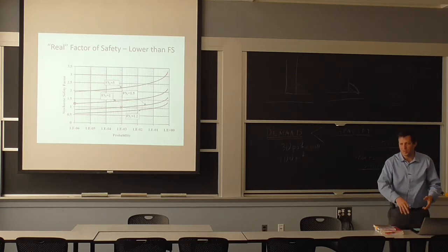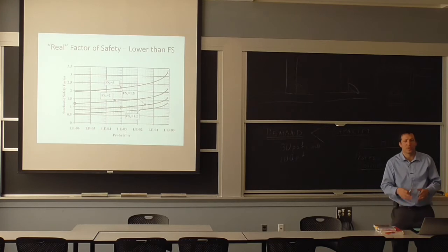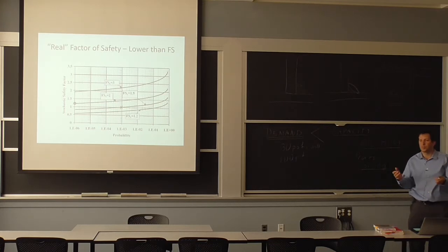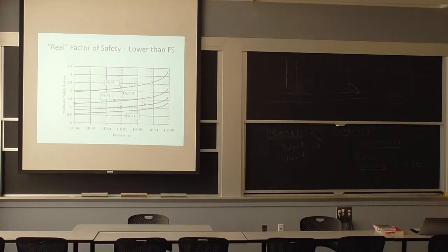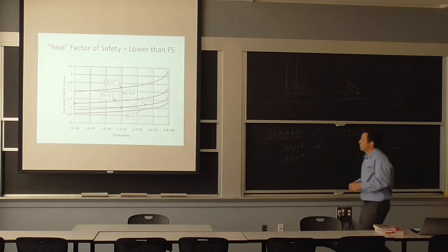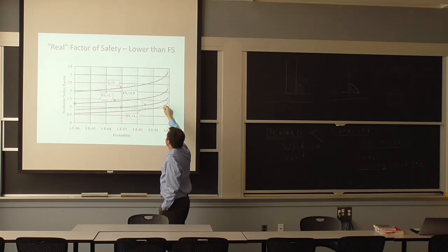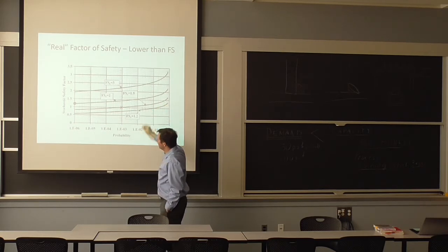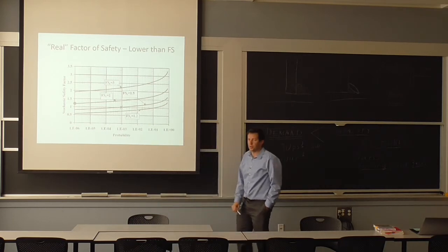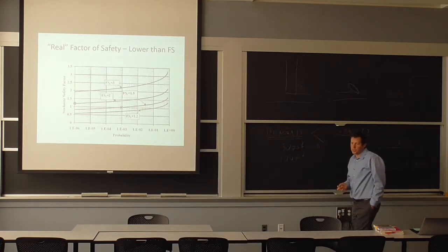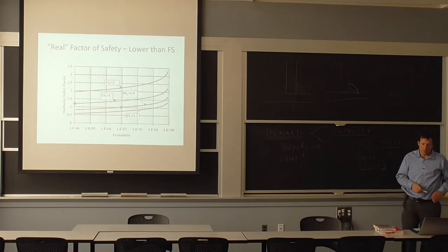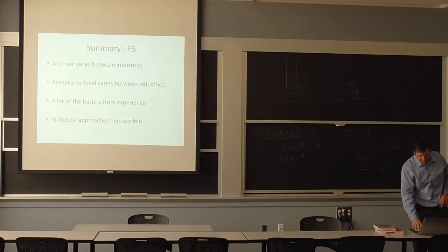I think everybody knows that when something is old, it's not as reliable, but there are ways to quantify that from service history, and there are very specific reasons. We're talking about rust, we're talking about slow cracking, fatigue, that essentially take the probability of failure of something from acceptable to not acceptable. If you load it a few times, or if this is a shorter service, you become below 1, and that is always true with everything we build. It's a little unfortunate, but it does happen.